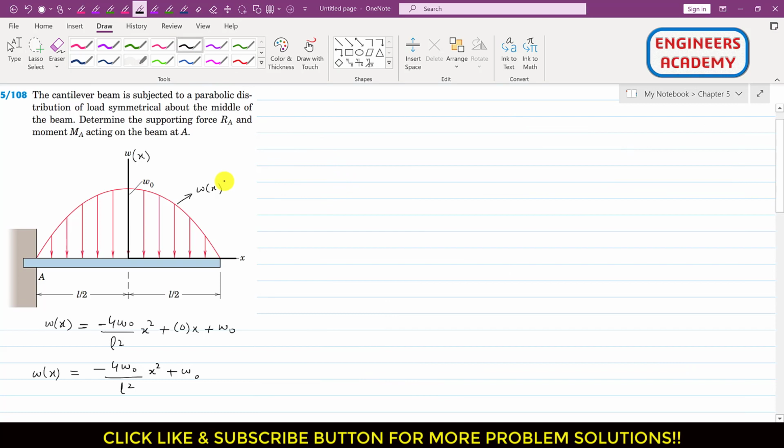So now the next step is that we need to find the resultant of this distributed load, that concentrated resultant which will replace this distributed load, right? So what we will do is that we will select a differential area. So for that I will select a differential area somewhere here. Let's say that this is our differential strip, and this differential strip is located at a distance of x from this origin, and this height is omega x, and this thickness is dx.